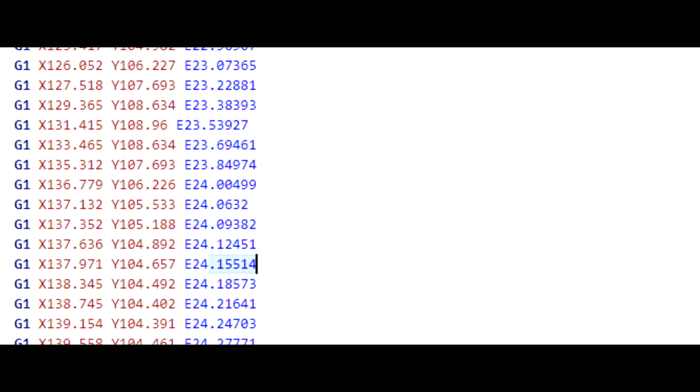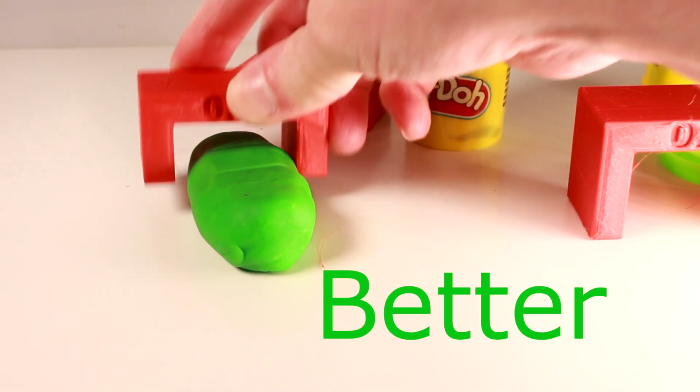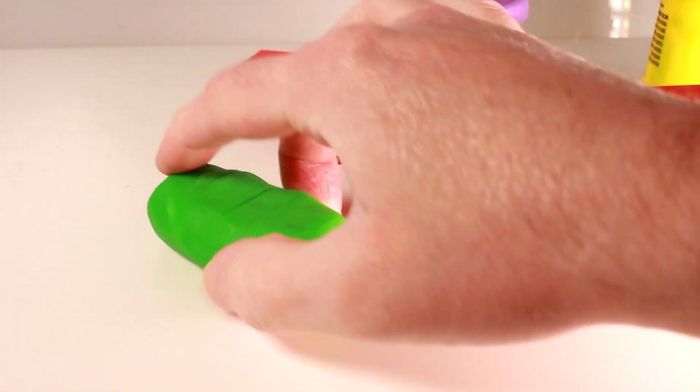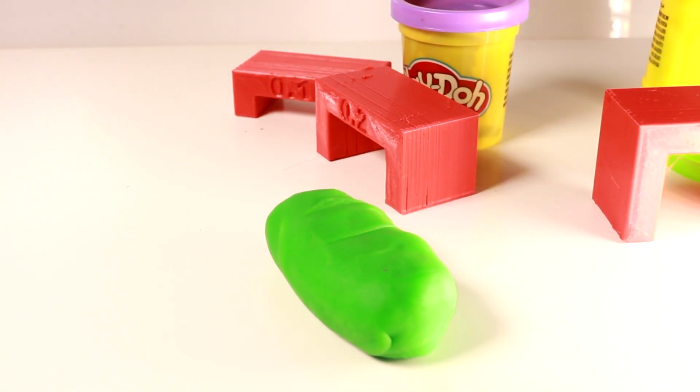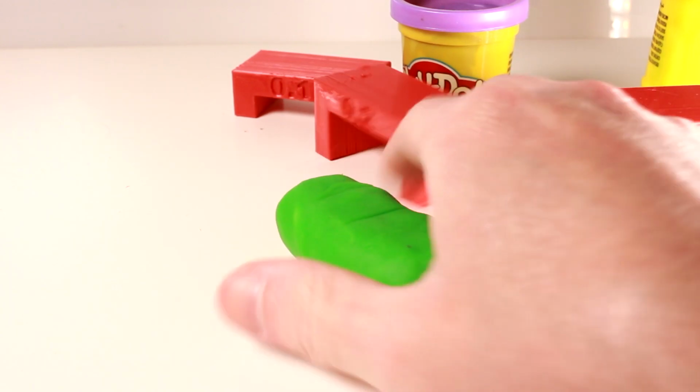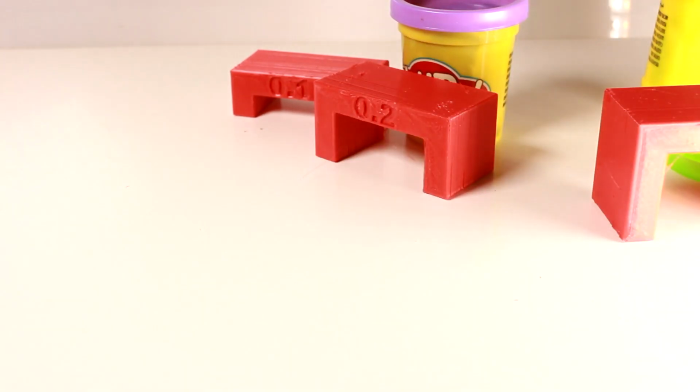Too much and you get over-extrusion, because more material has been pushed out of the nozzle than can fit in the line that it's occupying. Too little and you get a thin line, or you get intermittent lines, both of which are referred to as under-extrusion.